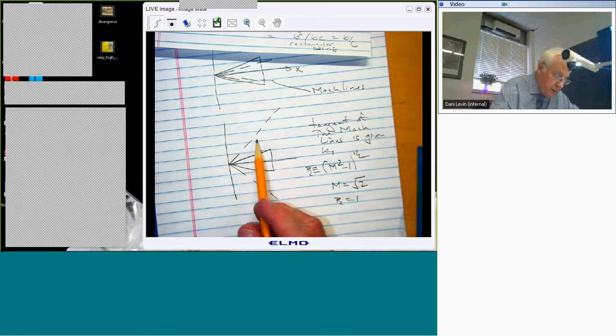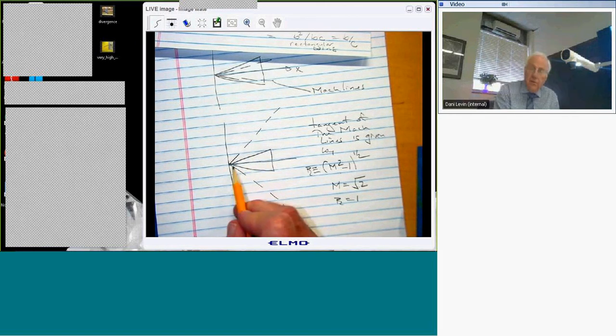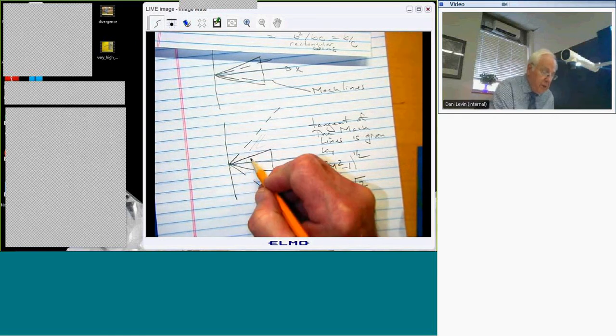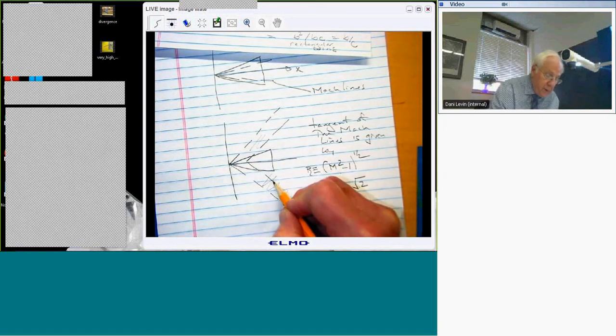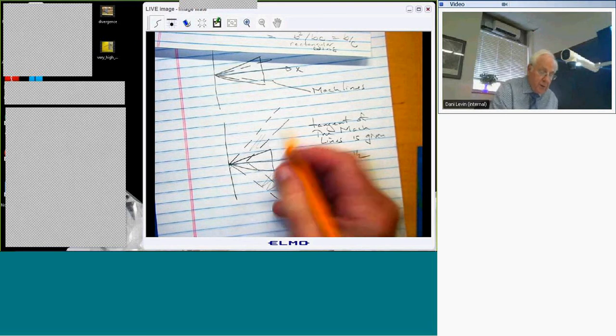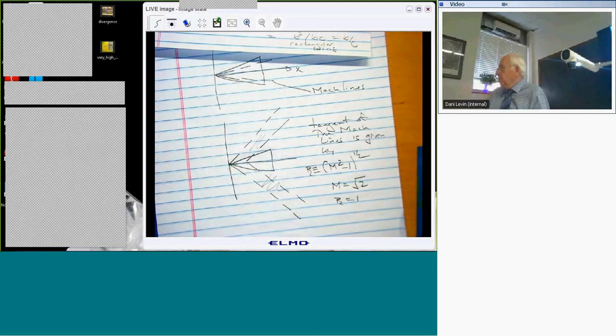What these Mach lines tell us is, because the airfoil is moving, including at this point, it's moving everywhere, but this is the furthest point forward, right? This means that the flow is going to be disturbed everywhere within these Mach lines, right? I could have another point over here, and it would have Mach lines. They'll be parallel to these, of course. So this point will disturb this and this and this. But the point is, this is the most disturbing point, because that's the one which governs the furthest expanse of the fluid that's disturbed by the motion of the wing.